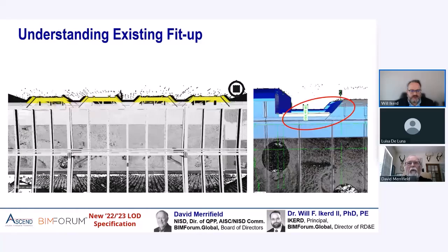And it's important that it is noted it's LOD 200 because it was approximate. There's no way that the modelers would be able to model it to LOD 300 on an existing building that they have no knowledge of what the real core of the wall is. In this case, no scan of both sides of the wall. The scope was to scan the outside. From those perspectives, it would be inappropriate to require laser scanning to provide an LOD 300 element, or worse, improperly state, I want an LOD 300 model from the laser scan.